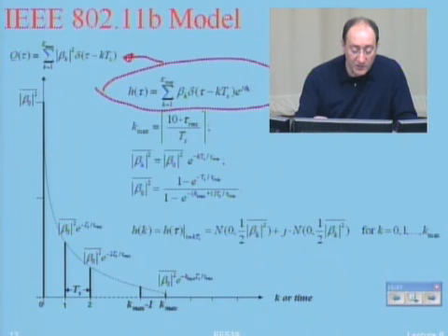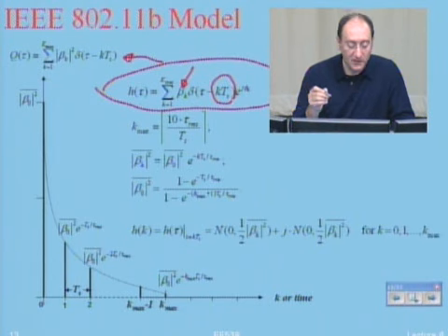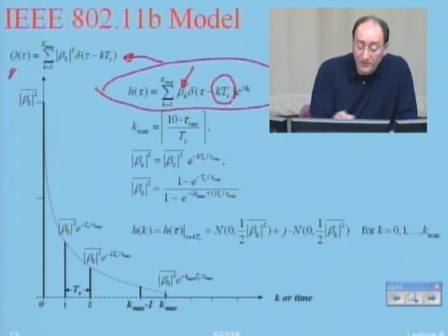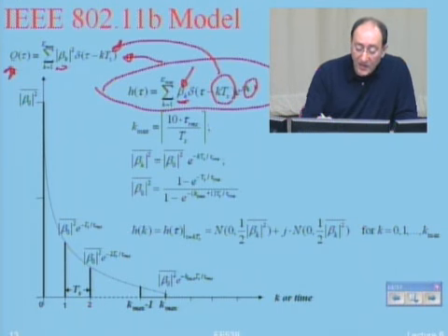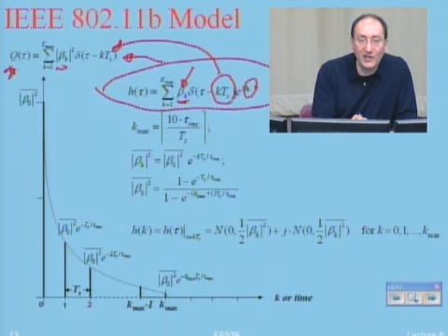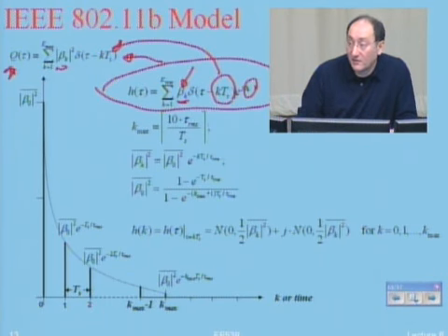The channel impulse response is defined by arrival times, the magnitude of paths, Q sub tau, plus the phase of the paths. But when you get Q sub tau, the magnitude is squared here, the time of arrival remains the same, and the phase you don't need anymore. So this is really the physical meaning of the delay power spectrum. It's a little bit simpler.